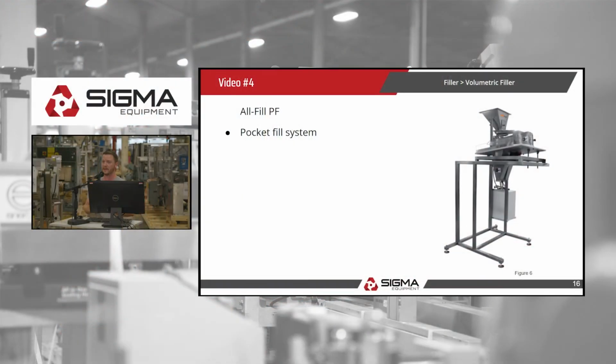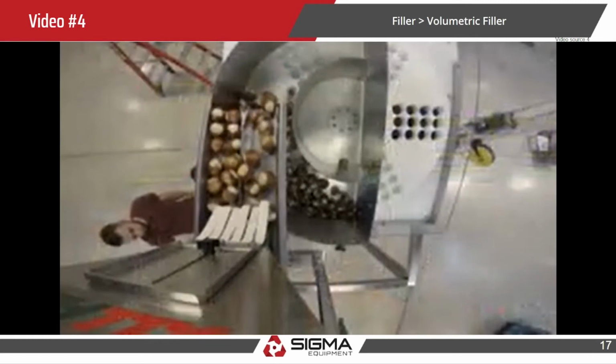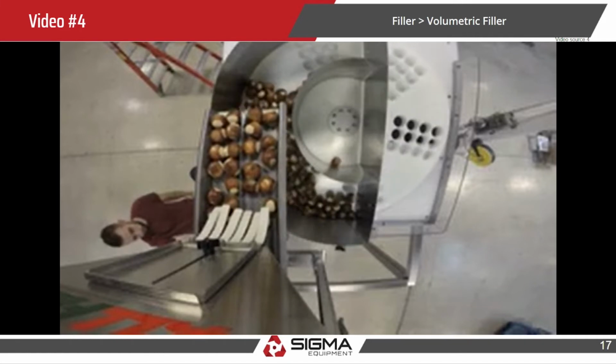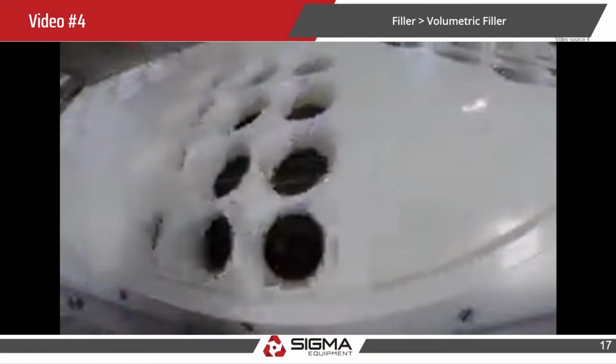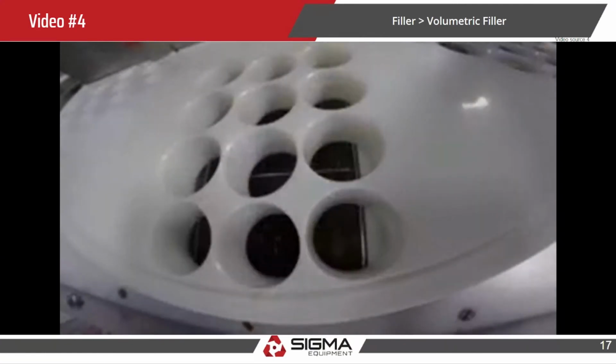One last video. This is a pocket fill system. This is actually going to have little pockets. If you're trying to get 5 pieces, 12 pieces of a certain product in there, it's going to have a pocket, and that pocket gets filled, and it drops your 12 pretzel bites every time. If you look right there on the right, you can see there's your 12 pockets, your holes. That's going to get filled every time as it comes around, and the top's going to get scraped. That way it's only those 12 that are getting put in there and then dropping down. And as you see, they're getting dropped, and it's getting just those 12 each time, so you get the constant amount.